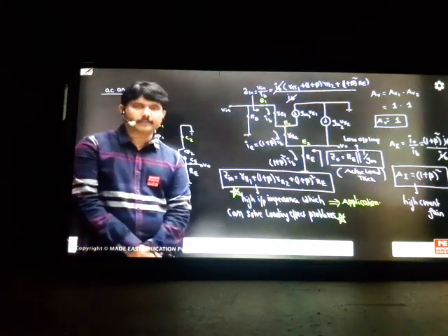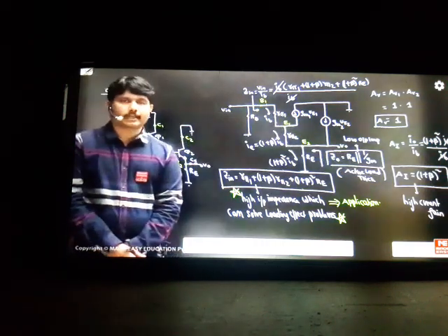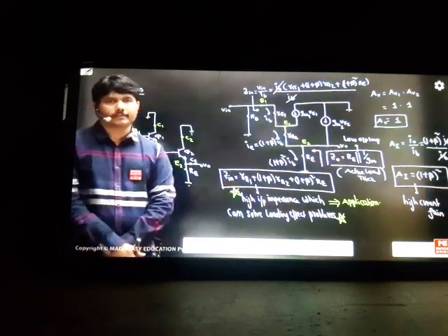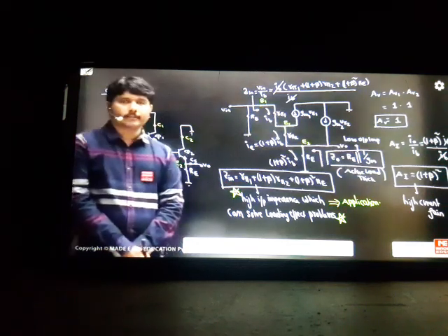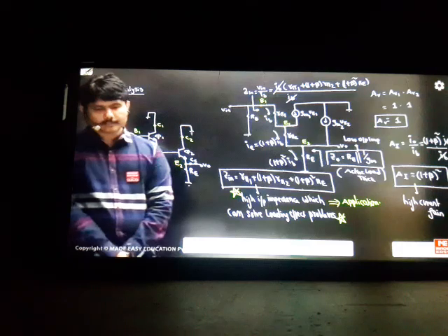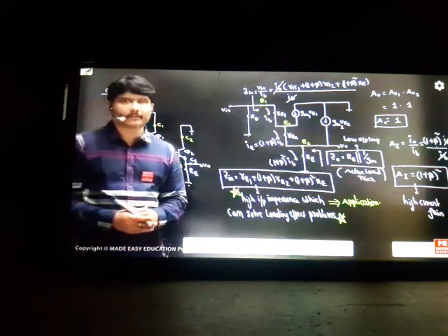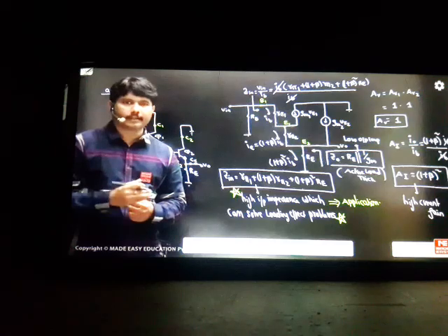Rahman, how can you say that power gain is high in this topic? How does power gain become high? Use a little logic. Voltage gain is 1. Current gain is high, but voltage gain is 1 here. Because one parameter is very low and the other is high, power gain cannot be high. If you want more power gain, both should be high. Here we are not interested in power gain in common collectors. Our interest is the loading effect problem solutions. This is my main interest. Unnecessarily don't make it a power gain concept. Power gain comes in Darlington cascode techniques.